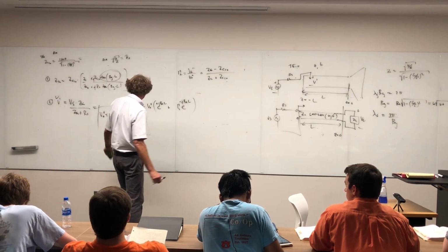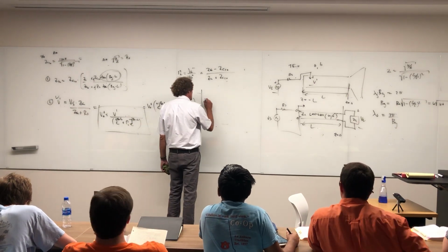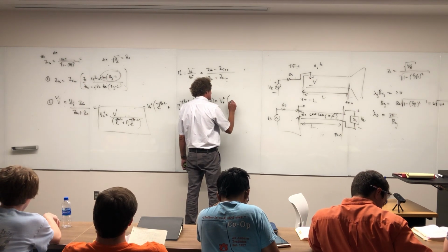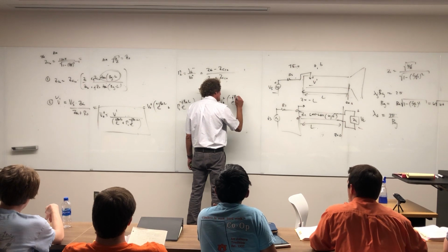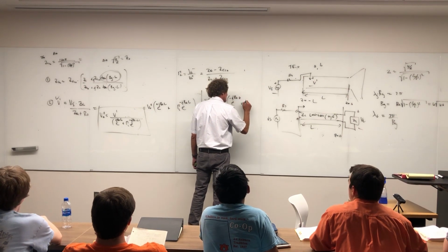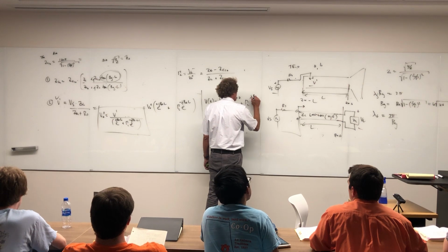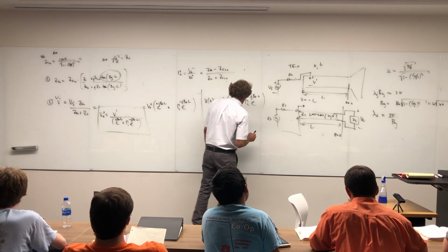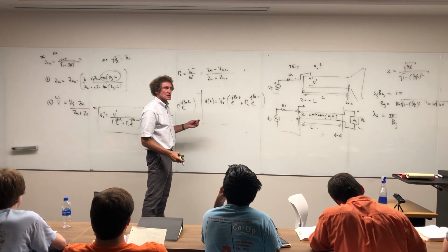So now I get this V0, and the general equation for voltage is V(z) is equal to V0 plus times e to the minus j beta z times z plus the reflection coefficient times e to the plus j beta z, or beta in the guide, times z. So I have gamma, I've got V0 plus, and now I want the voltage at the load.